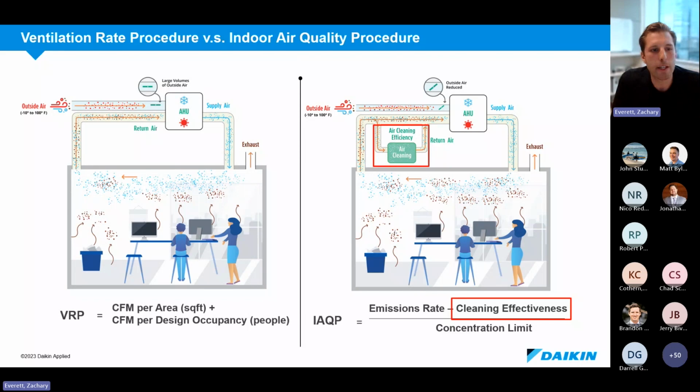Unfortunately, that means that if we want to improve, not just keep the status quo, but improve the indoor air quality that we have in our spaces, we have to bring in more air to do that, and we have to exhaust more air. And you say, wait, we have energy recovery wheels. Isn't that effective? Yes, it helps certainly, but we're still treating that air, even though we've captured some of the heat or cool, even latent energy.